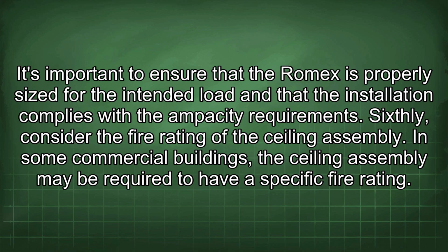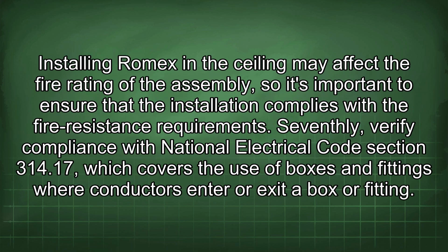Sixthly, consider the fire rating of the ceiling assembly. In some commercial buildings, the ceiling assembly may be required to have a specific fire rating. Installing Romex in the ceiling may affect the fire rating of the assembly, so it's important to ensure that the installation complies with the fire resistance requirements.